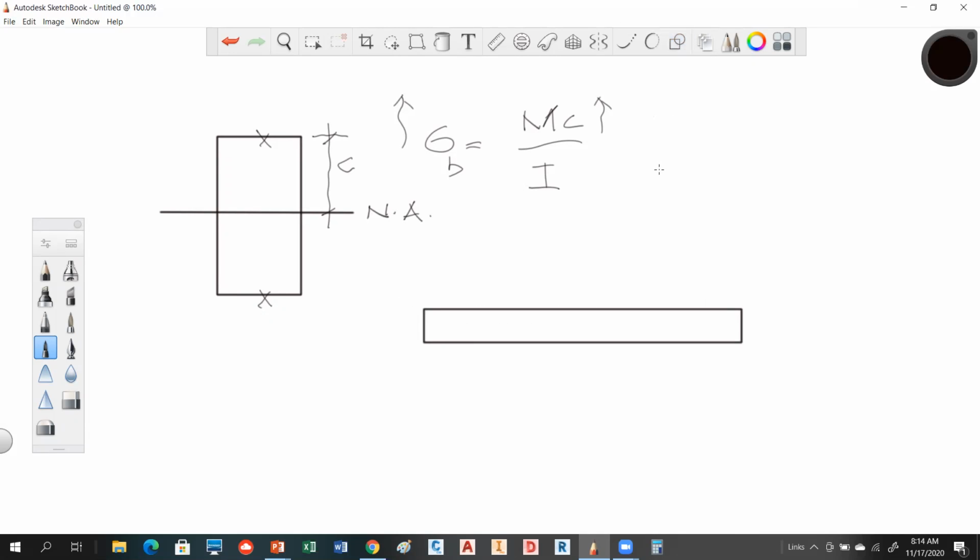What we're looking at there is, remember, if you have a force coming down on this guy, it's producing a bending moment, okay? And so that the beam doesn't rip apart or deflect too much, the material has to develop stresses in here to counteract that bending moment. So this is a counteracting thing that will counteract the applied moment, okay?